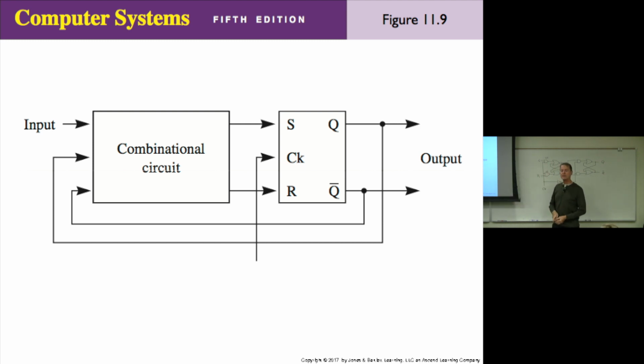Do you see what we have to do? Do you do like an enable with the clock, kind of? Or a disable? But the clock has got to be high for... You might try to spike the clock and just have it be a tiny little width, so short that it wouldn't have time to go around on the feedback.